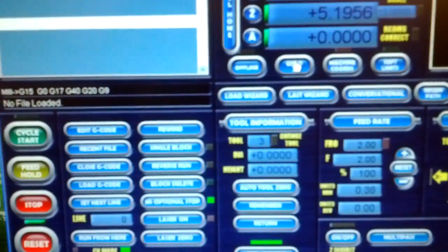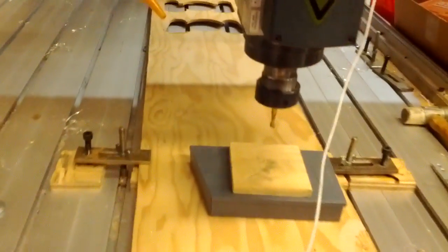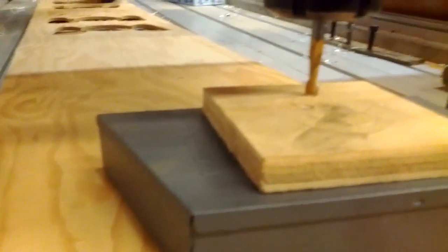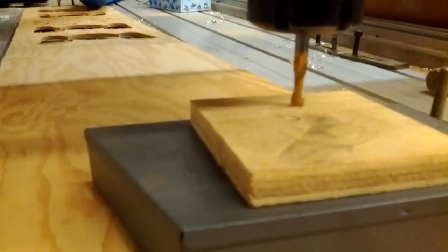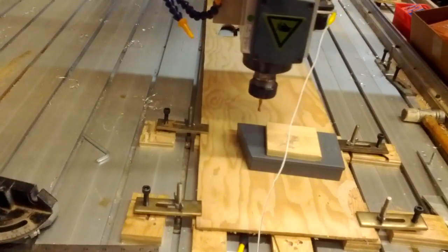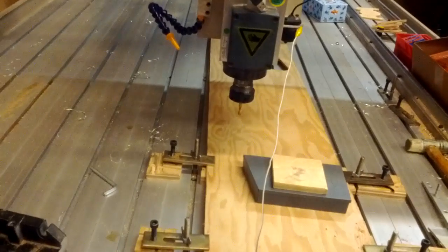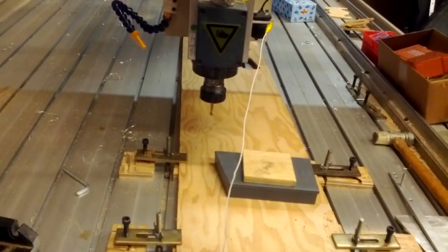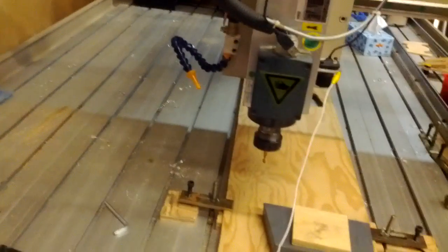And the nice thing is, when I click on the go to 0 button here, it will go down, down, down. Just touch it, because it knows how thick that plate was, that movable plate. So just touching it there. So let's say, for example, now I'm cutting or I run the spindle for a little bit, and I change the Z and X and Y directions. And I need to do a tool change.